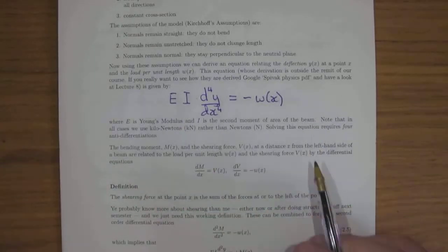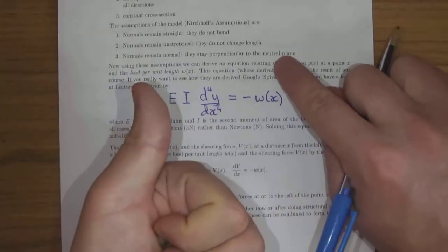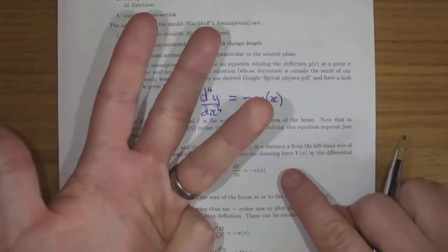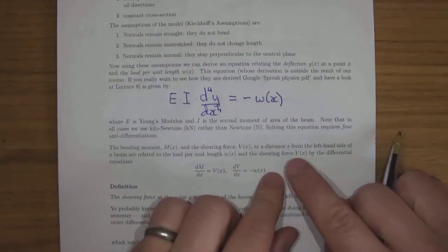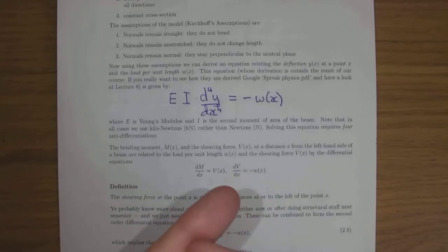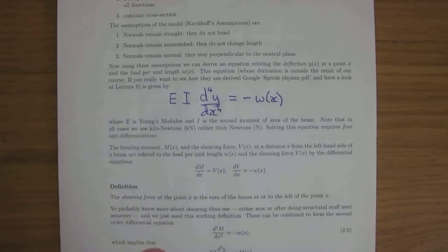Okay, now to solve this, you have to anti-differentiate 4 times, from the fourth derivative to the third derivative, from the third derivative to the second, from the second to the first, and from the first to find the deflection. Now every time you anti-differentiate, you'll pick up a constant. Now we're going to learn that the constants are, the first is the reaction at A, the second is the bending moment at A, where A is the left hand side of the beam, the next one we call C1, and that is related to the slope at A, and the last one is C2, which is related to the deflection at A, which for us will always be 0.